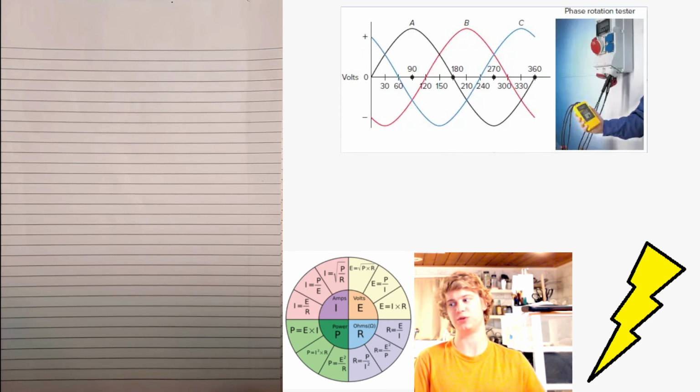A three-phase distribution system can be used to supply both three-phase and single-phase service. A three-phase alternator contains 3 sets of coils positioned 120 degrees apart, and its output voltage consists of 3 voltage waves 120 electrical degrees apart. The order in which these voltages succeed one another is called the phase rotation or the phase sequence.